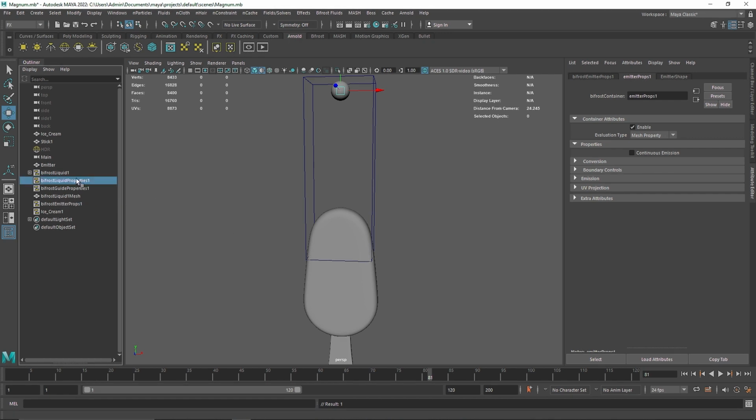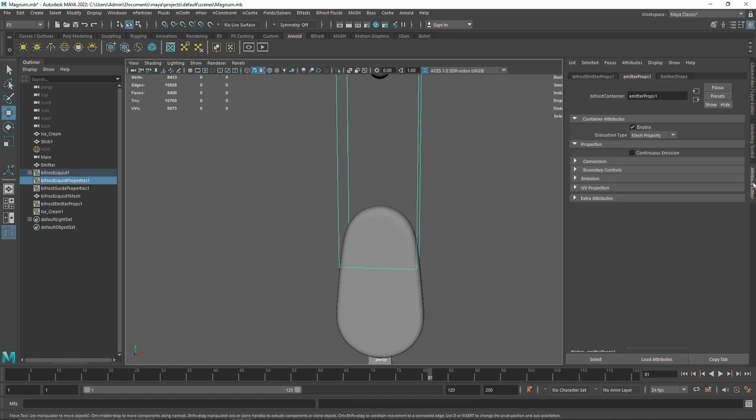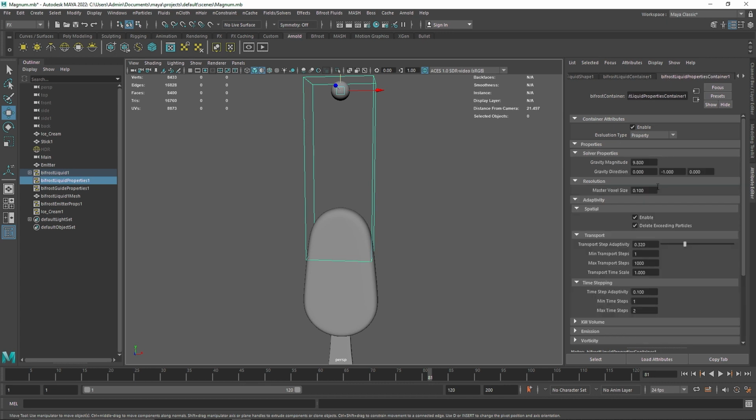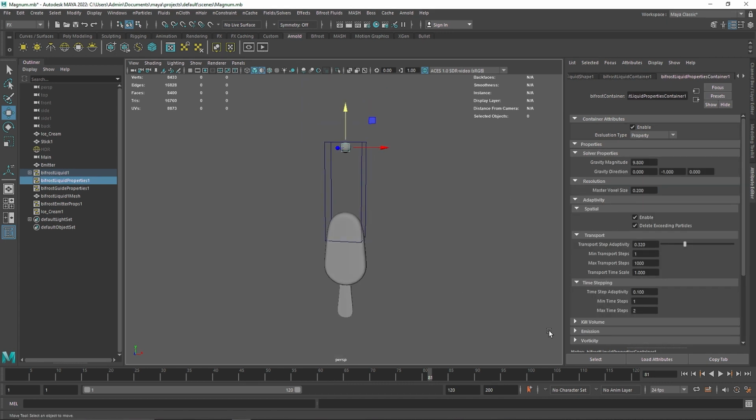So that means I'm going to just lower the resolution on this so we can see a bit better how our simulation is looking with continuous emission being animated. So let's bring this back, turn this on. And so this is our liquid pouring out. It's going to keep pouring out a lot of chocolate. It's going to keep going on and on and on. And as it reaches the 75th keyframe, it's going to stop.